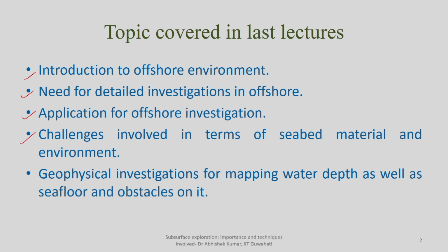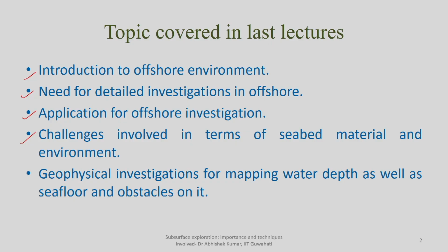So, what are the challenges involved? We discussed stability, because it is not only about the resistance the seabed material offers against external loading, but also the environment created at the seabed, whether it is related to a ridge, a shelf, or the continental margin, and depending upon the extent of water depth, the seabed topography and seabed obstacles. These can induce more challenges which have to be highlighted, understood, and clearly assessed before we go for actual erection or laying of the foundation for the proposed structure.